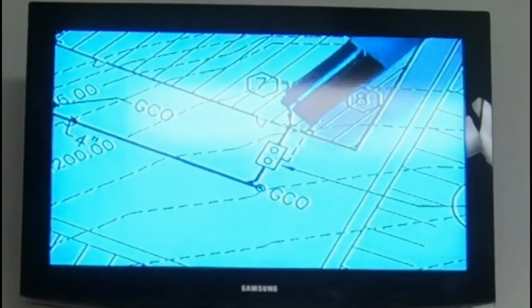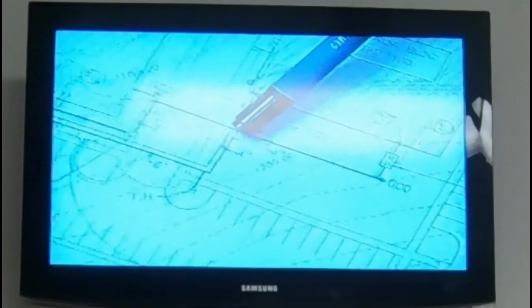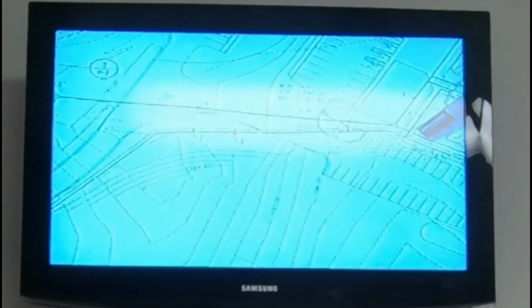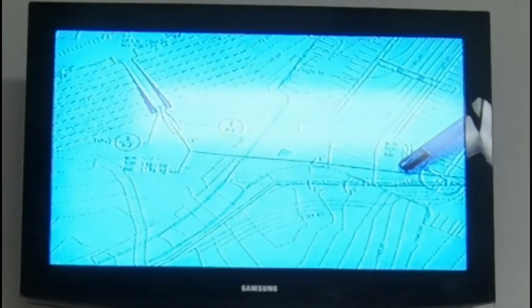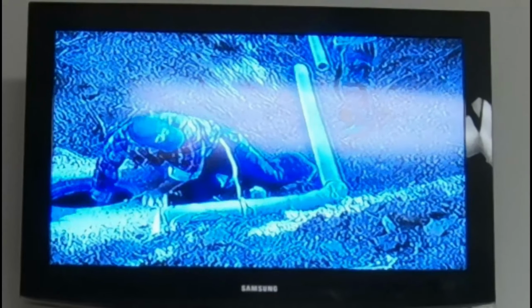to a system in excess of 50 milligrams per liter. When grease traps are required, the effluent from the grease trap shall be deposited into the septic tank and not directly into an absorption field. Beginning at the house, all solid pipe fittings shall be Schedule 40 PVC or equivalent and shall be a minimum of 4 inches in diameter. All septic tank openings must be sealed and watertight.